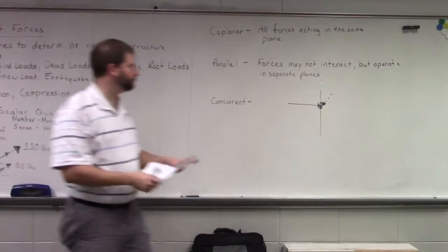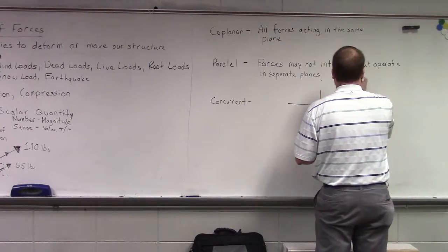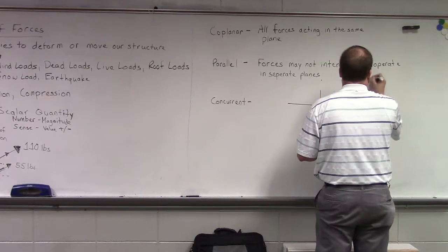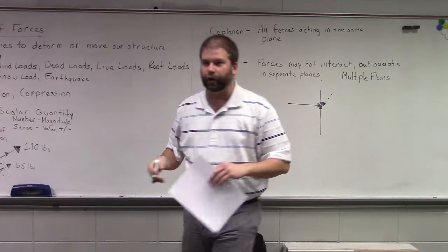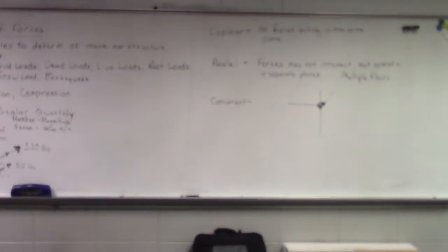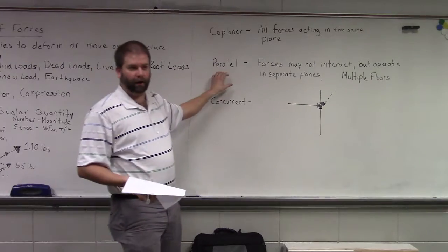Multiple floors, right? We could also have the vertical components of resistance of a structural wall, and maybe we also need a shear wall that does take a little bit of vertical loading as well. So as long as we're only considering the vertical components of that construction, we would be investigating parallel forces.